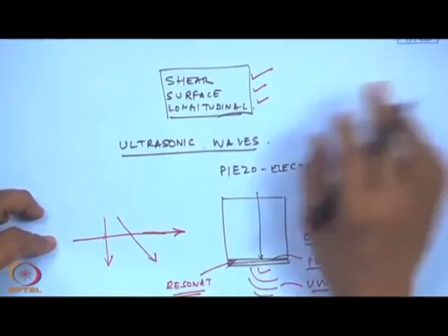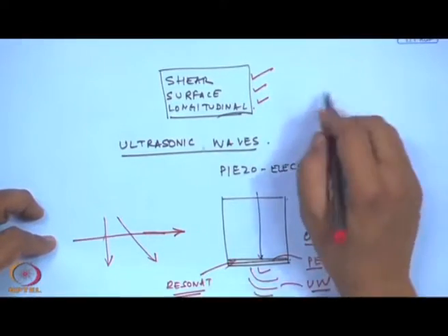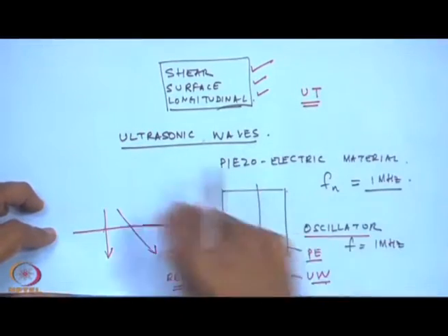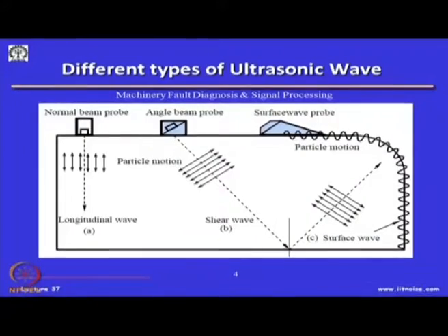So, once such waves have been generated by an ultrasonic transmitter, we can have this wave propagating in a material. Depending on the impedance of the material, because of a defect, discontinuity, void, or crack, we can get a reflected wave. Depending on the intensity of the reflected wave in comparison with the intensity of the incident wave, we can get a clue as to what is the change in the impedance and where the defect is, and so on.